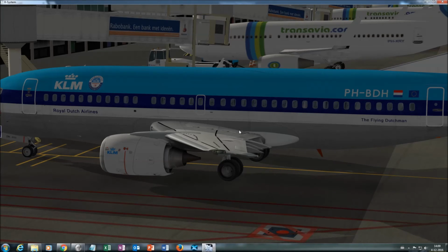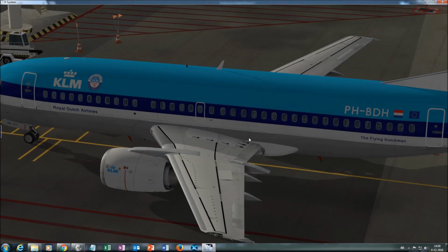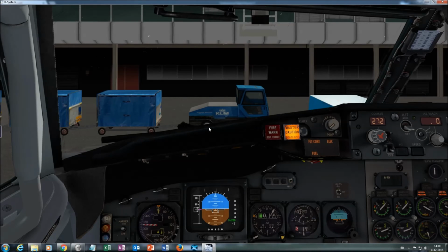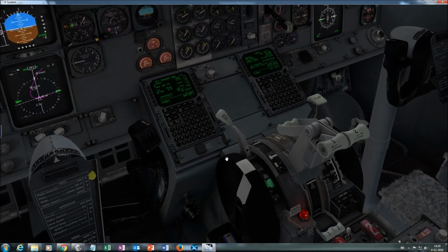So the airplane engineer said, well, let's make movable surfaces that will increase the surface area of the wing and the curve of the wing when we need it, and that we can retract so they don't give drag when we don't need them. And that's why on landing you see the flaps extend so you can fly slower, and during cruise the flaps are up so they don't create drag. That's basically the point of flaps. In a nutshell, oversimplified but kind of correct.